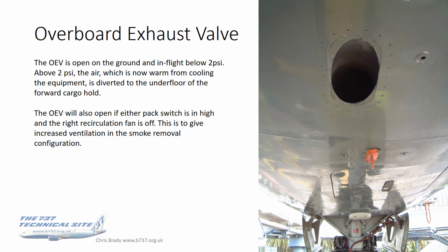I never seem to hear it closing, but I guess that's because it closes in the climb, and in the climb the flight deck's a lot louder because the engines are obviously at a higher thrust. But certainly on approach you notice it. So next time you hear this hissing sound suddenly occur on the approach, just have a quick look at the cabin diff pressure, and you should see it's around 2 psi.